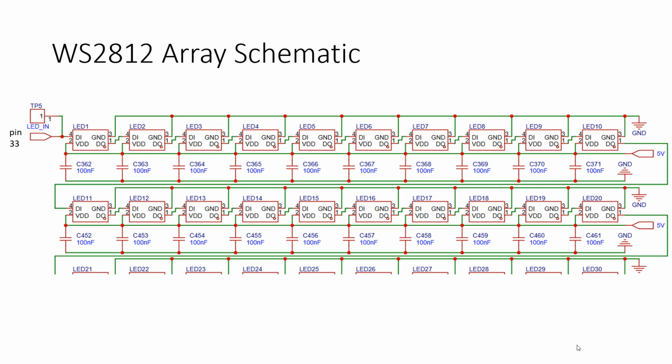So it creates this chain very similar to a JTAG chain, or also, remember when we talked about daisy chaining SPI connections, the idea is similar to that, right? When you have a SPI, you have MOSI going out, and then the MISO coming out of the first and going into the MOSI of the next, and so forth. This is the same idea, except we just have data in and data out, right? So we can control all these LEDs from one pin.